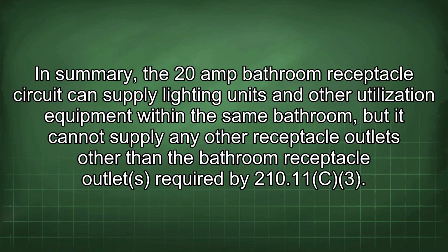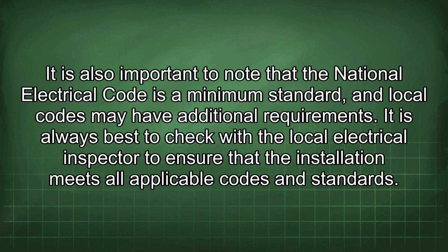In summary, the 20 amp bathroom receptacle circuit can supply lighting units and other utilization equipment within the same bathroom, but it cannot supply any other receptacle outlets other than the bathroom receptacle outlets required by 210.11(C)(3). It is also important to note that the National Electrical Code is a minimum standard, and local codes may have additional requirements. It is always best to check with the local electrical inspector to ensure that the installation meets all applicable codes and standards.